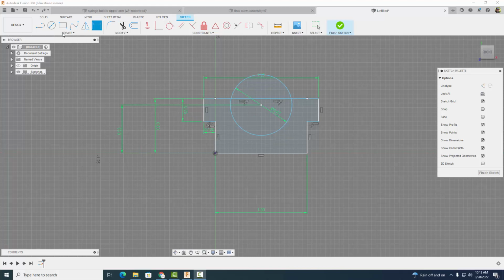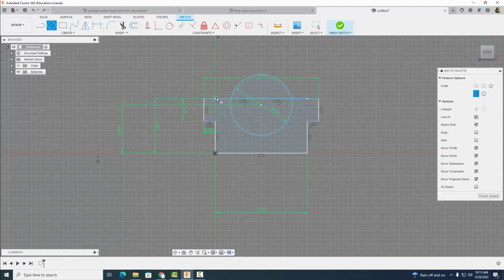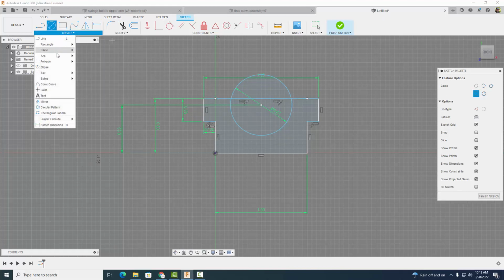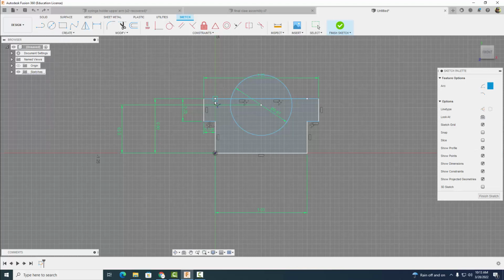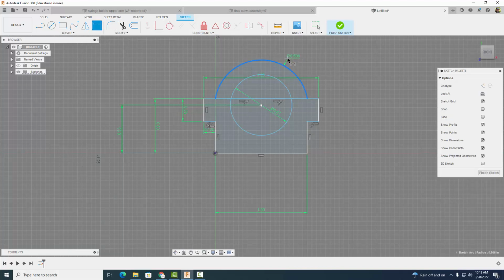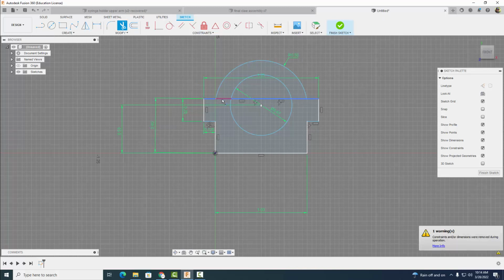Now let's go ahead now and make another arc. So, I'm sorry, not a circle, an arc. Come on down to 3-point arc. We're going to click here. We're going to click here. And we're just going to kind of drag out something that looks like this. And we're going to dimension that guy to have a radius here of 0.5. Okay, and now let's go ahead and trim some of these lines up.